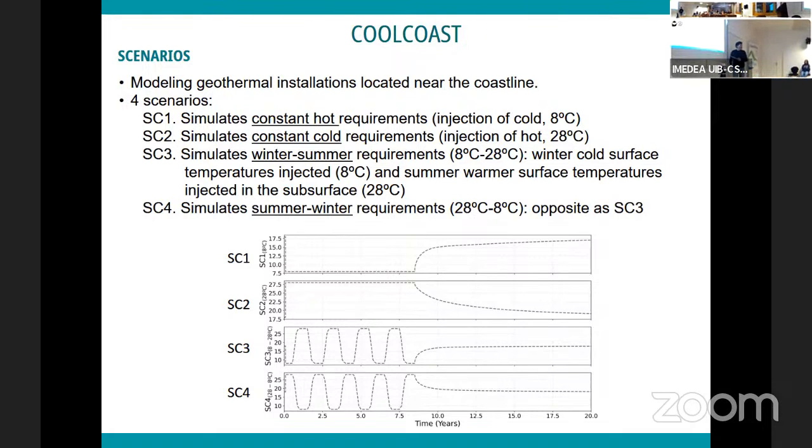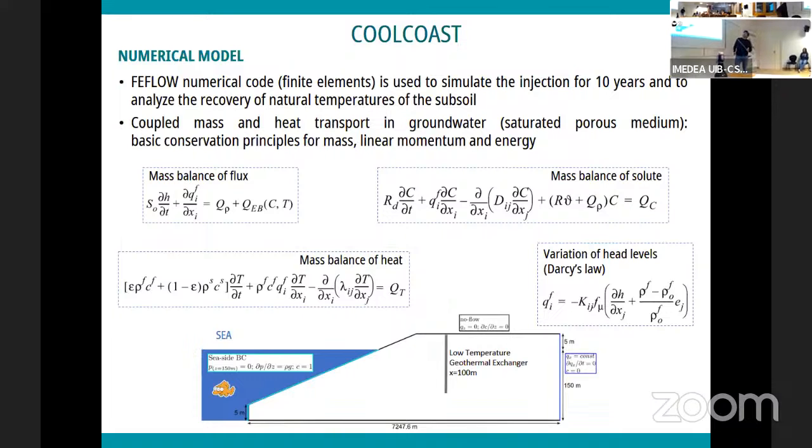After 4 cycles of these injections, we stop the operation and see what is going on with the temperature of the groundwater: how is the recovery of the initial temperature, what time it takes, and what is the shape of this recovery. Okay, so I use the FEFLOW numerical model code to couple the mass balance of flux, solute, and heat, and all are coupled through the difference of density and difference of temperature. Okay, this is the setup of the model.